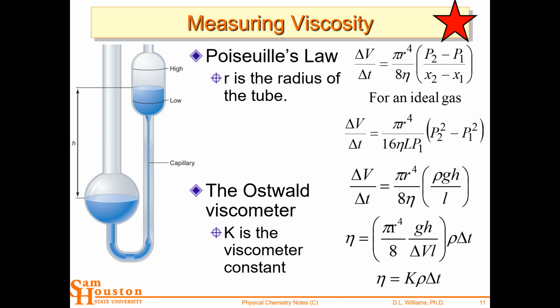Oh, that's what... So it could go underground and come back up, and so it's the difference between the reservoir level and the exit. Yeah, okay. And that's how siphoning works. So with siphoning, you just have to get the exit lower than the level, and so it can go up too. But if it comes down again and gets below the level, then you've got a head pressure there, and then you'll get flow. And if you want to double the flow, double the head distance.